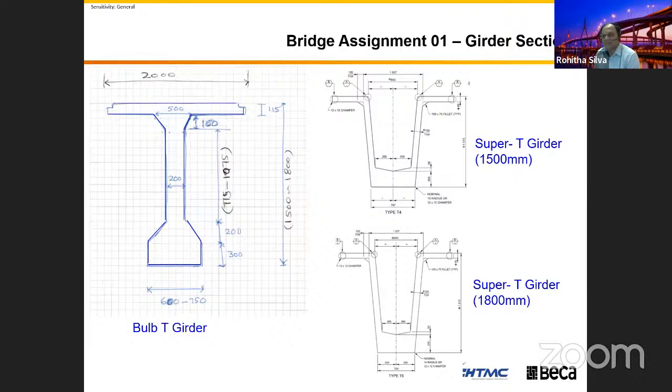The reason is, when we design bridges for a predefined speed, like let's say motorways at 100 kilometers per hour, at least 80 kilometers per hour, the vertical gradient is actually a geometric design to get the sight distance depending on the vehicle speed. There are limitations in that. Superstructure selection is not going to be affected that much when we are selecting the girder type.